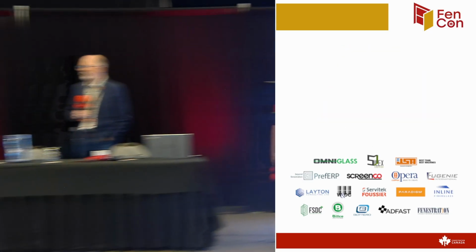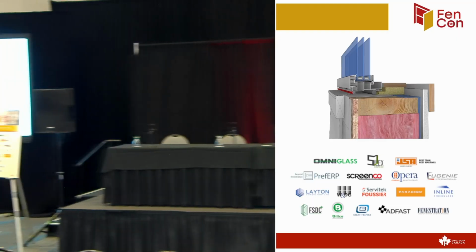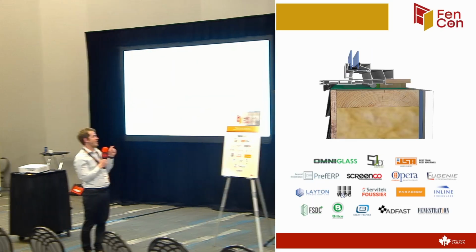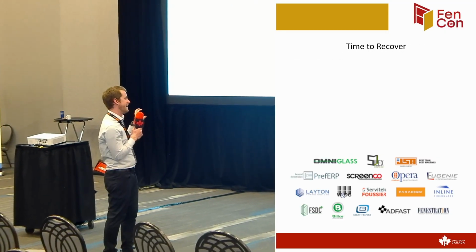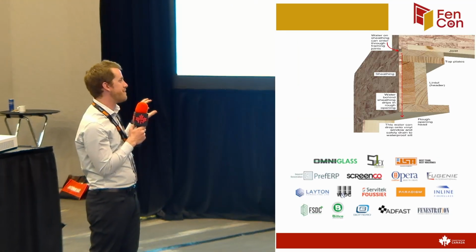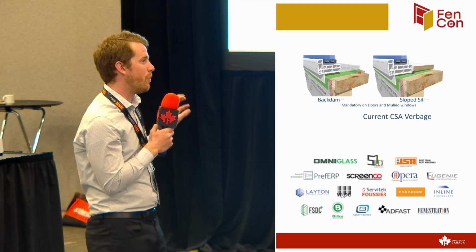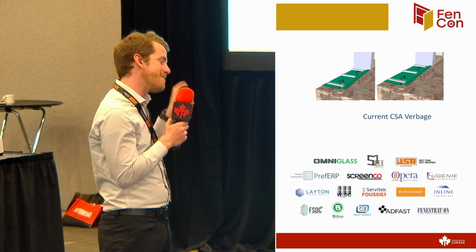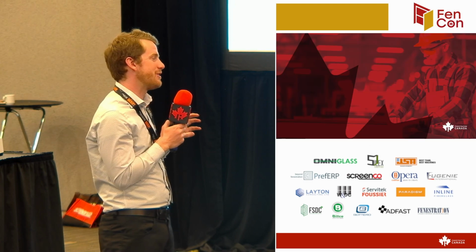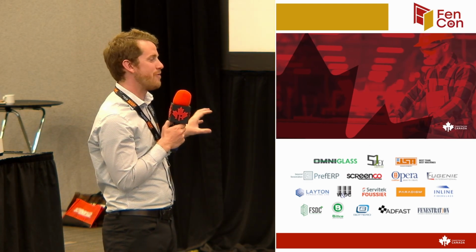So if you have exactly what you're talking about with the spray foam and you've cut the outside face, they're acting as little straws that are essentially holding on to the water, and then you've got that up against potentially an air barrier, not something non-permeable. So why would you lean on the safe route of adding insulation to the rough opening cavity?